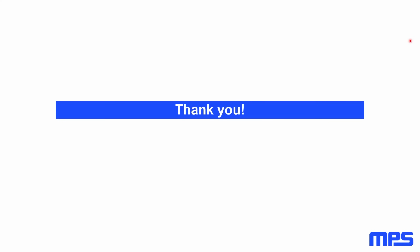Let me just perhaps extrapolate a little bit. The I2C is more robust, let's say, than the SPI. We see different customers around the globe really preferring to use the I2C also from the EMI perspective. When we have some BCI, bulk current injection, the I2C seems to be more robust than the SPI. So the I2C in general is much better in these use cases. Yes, I agree. And I think it also just depends on the number of IOs that are available for you guys anyway. Okay, no problem.